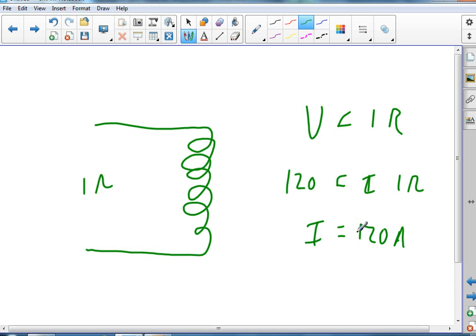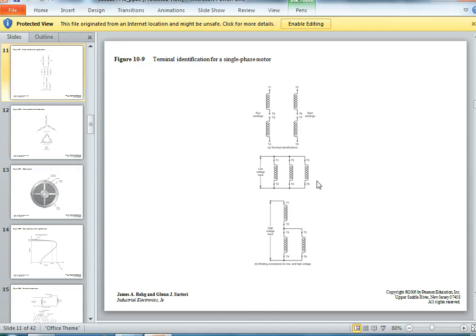Now, once the motor starts rotating, the magnetic fields are forming there and there might be a change in voltage from my input voltage. The motor is acting as a generator. It's generating a back EMF. Now instead of having the 120 volts difference you had when you turned it on, you may only have a 2 or 3 volt difference, because the back EMF of the motor might be 115 volts, and now you have 120 in, 115 being generated by the motor. There's only a 5 volt difference. Now you're not going to draw as much current.